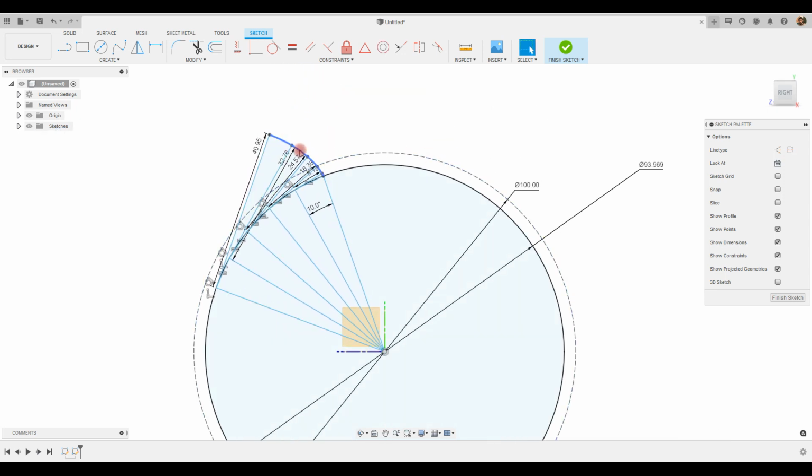So the next step would be that this profile, this spline which we created, we have to create another mirror spline on the other side so that we can create the tooth space. So the space between the two tooth, that is to be modeled, and that will be cut from the solid of an addendum circle. So that's the workflow.